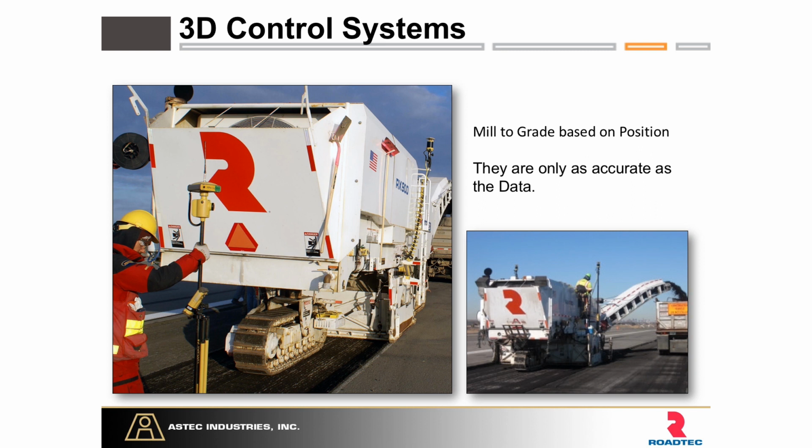3D control systems. Oftentimes these are required for airports. These require additional equipment that you might see more in the surveying field. But this is excellent technology. It's within millimeters of accuracy, but it doesn't come without a learning curve. So I would recommend when these jobs are requiring 3D milling or this sort of technology that you have someone from your local provider, such as Topcon, Trimble, or Leica. These are manufacturers of this system. It's a good idea to have someone from there on your site to make sure that you've got everything hooked up properly and everything's working right.